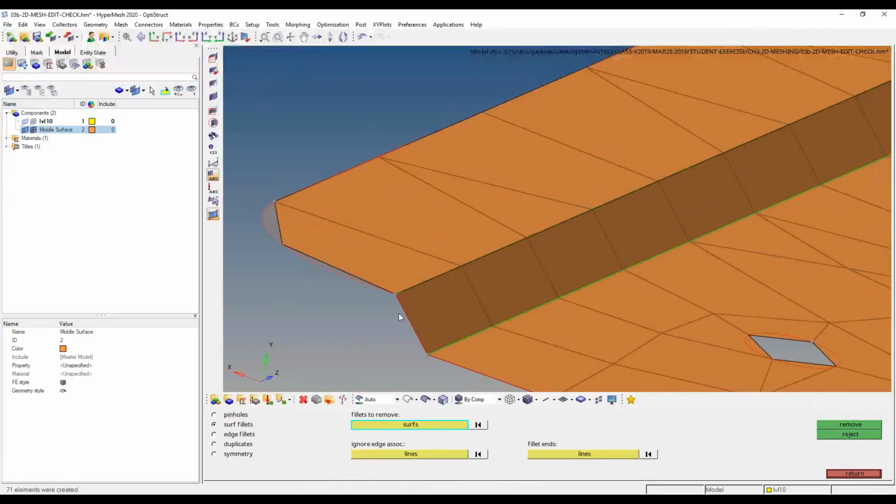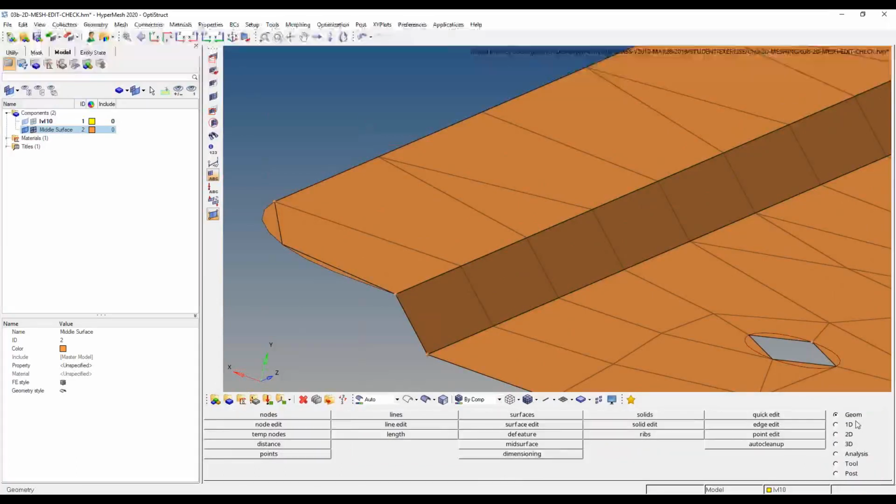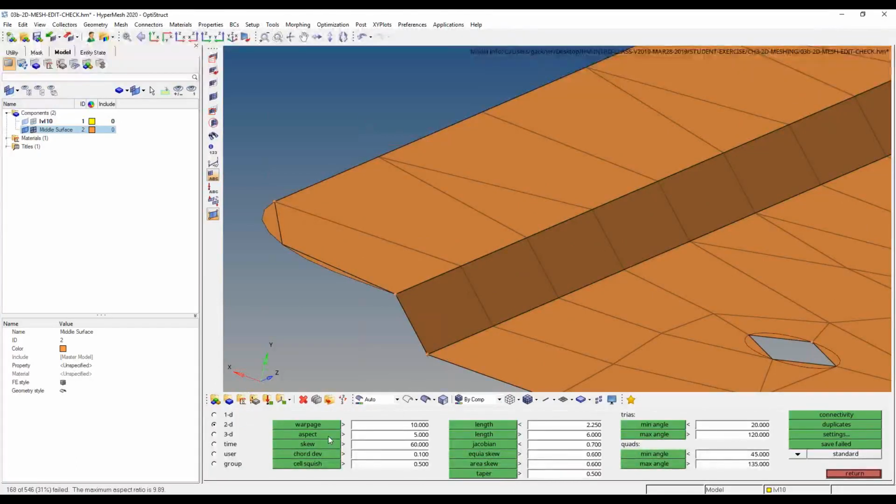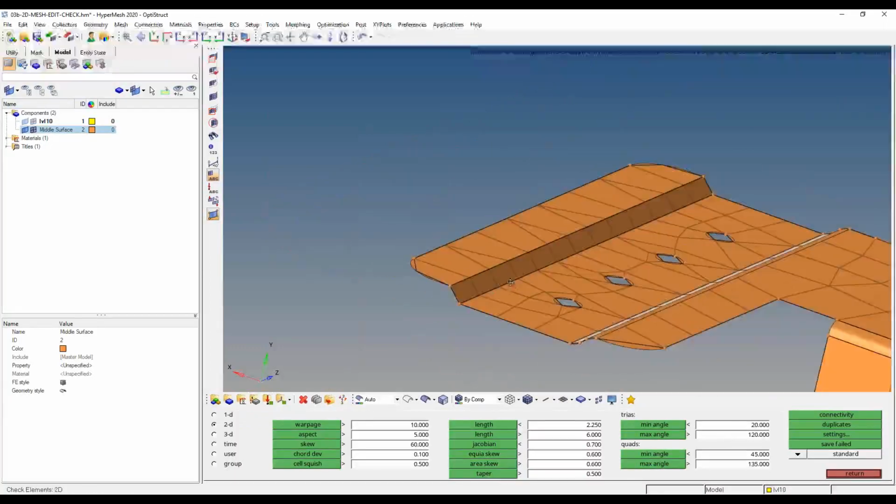And you'll see HyperMesh actually went back and automatically meshed the part around those. And sure, I lost some of those curved features, but maybe in this analysis I didn't need to see any stresses at those fillets, and I just needed to model this bracket in with some weight. I don't need to see the perfect curves there. And as a result, if I come all the way back to my quality check, I don't have failing aspect ratio elements along that interface anymore.